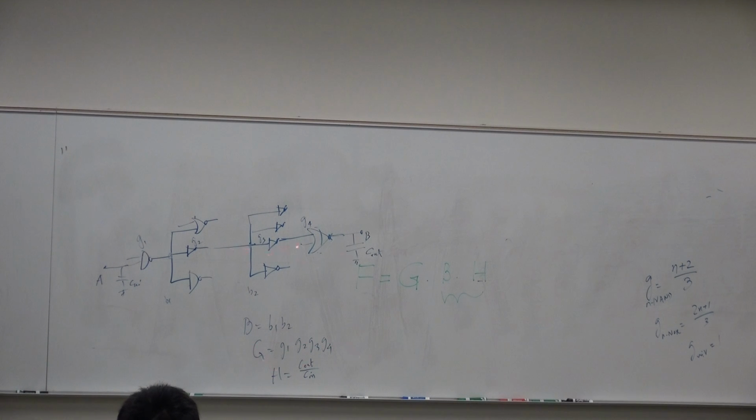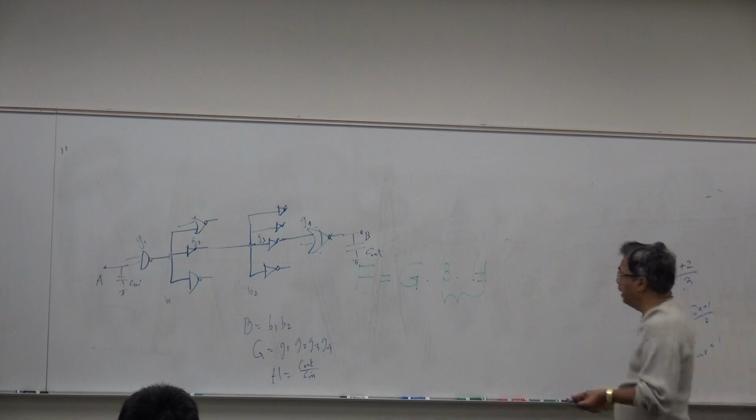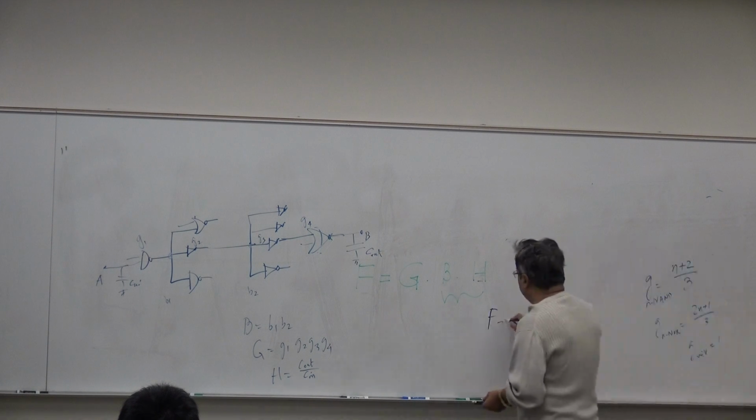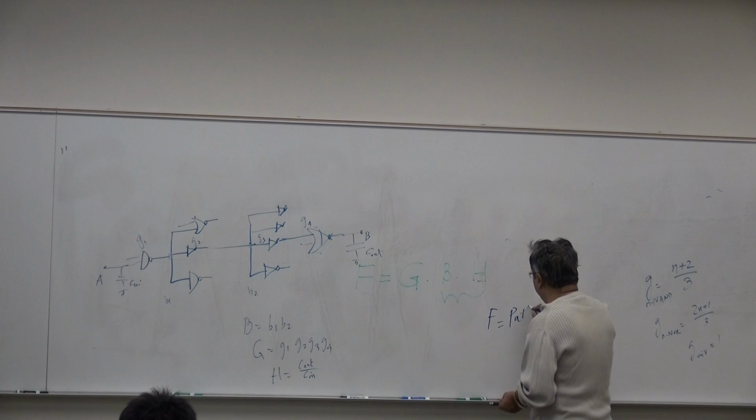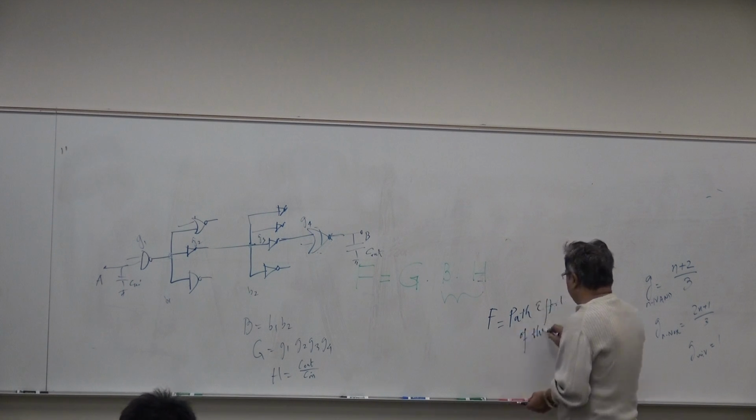Looking at the netlist, the branching, we can calculate B. And this capacitance and this capacitance are given, you can estimate by parasitic extraction. So you can calculate this. So now you have the expression for the path F4 of the logical network.